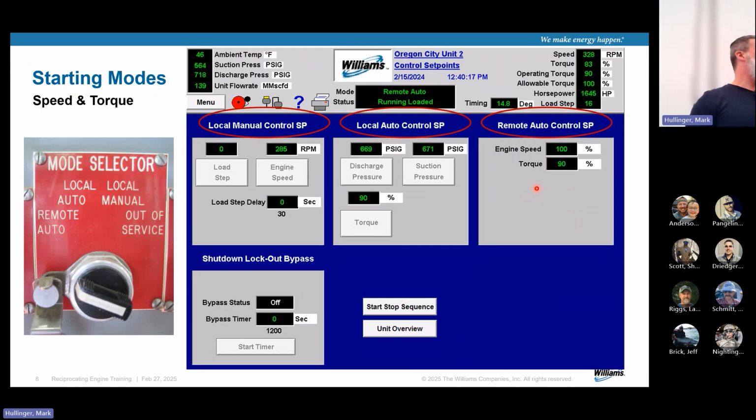Gas control, what was that? Oh, I thought your torque would be a value of your thermal loss. Oh, yeah. This is a set point the gas control puts in. On another screen, it'll actually show you your horsepower, and we don't actually display those losses. So the engine speed and the torque are put in by gas control, and they're doing this remotely based on their nominations.